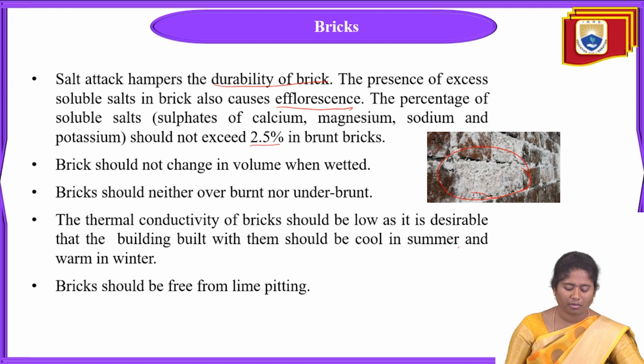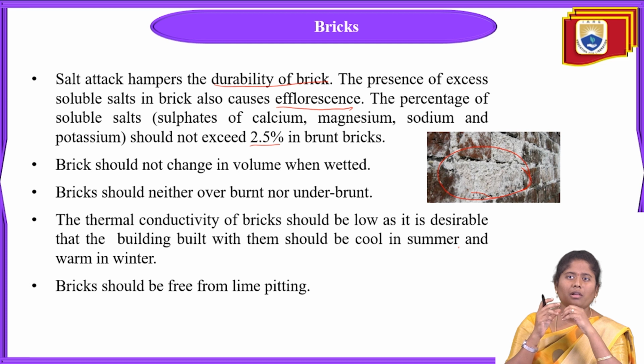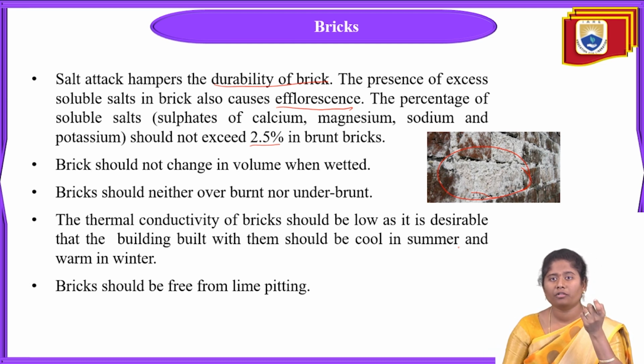And the next one is that it should be free from lime pitting. If the brick contains calcium carbonate, it will lead to the development of quicklime. What is lime pitting? When there is calcium carbonate in the brick, it slowly leads to an excess amount of quicklime.